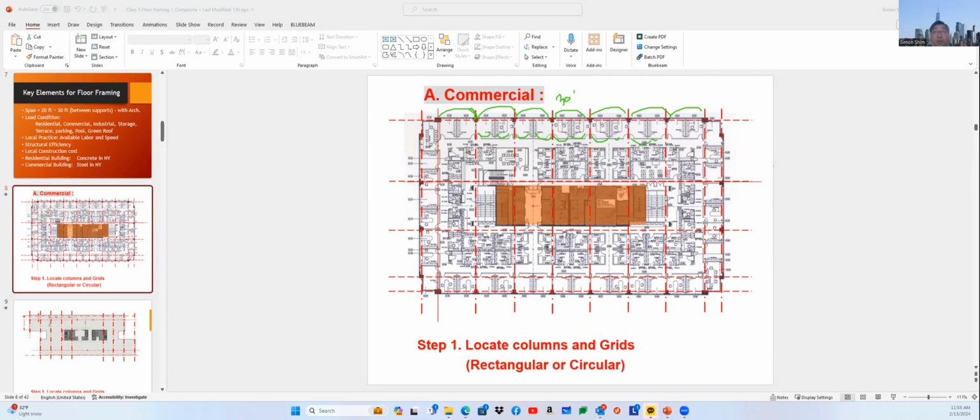I think it's pretty old, an existing building, but it gave us some idea of uniform column spacing. At the end, obviously, the building footprint is not as big, so they introduce another grid at the end of the buildings. Also, you notice that at the corner of the building footprint there is a recessed slab, which is part of the architectural design intention.